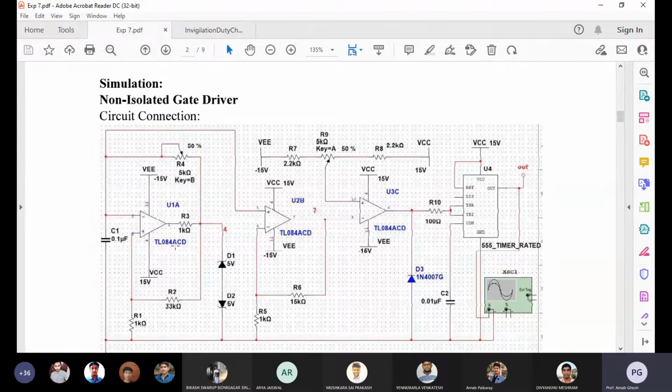You know that the power circuit can be in the megawatt range, but in your control circuit the maximum biasing voltage is around 18 volt. Normally we are using 12 volt and 15 volt; those two are the standard. So the op amp can uplift the gate pulse up to 15 volt, but the power circuit can be handled in the megawatt range.